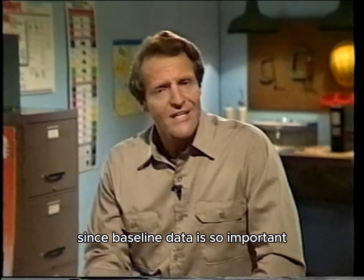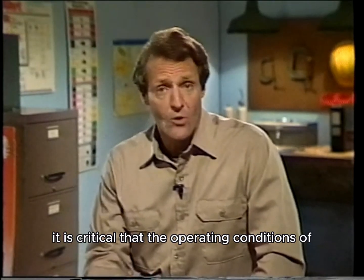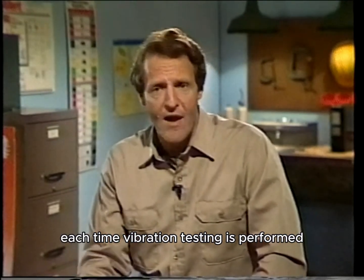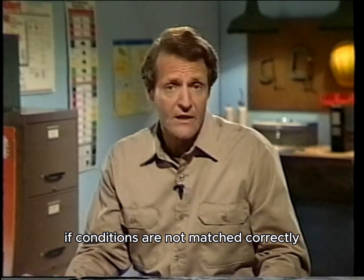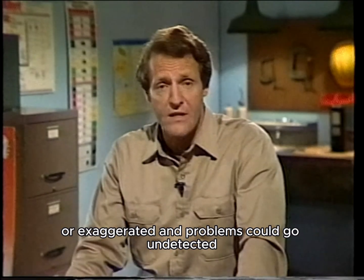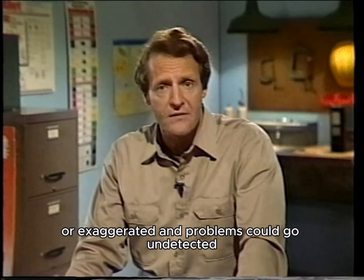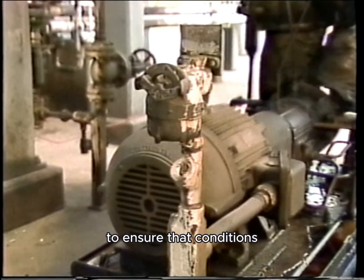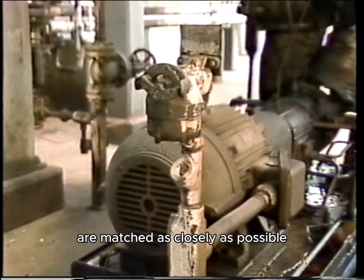Since baseline data is so important, it is critical that the operating conditions of the machinery are the same each time vibration testing is performed. If conditions are not matched correctly, the actual vibration of the machine could be masked or exaggerated, and problems could go undetected. There are many parameters that should be checked to ensure that conditions are matched as closely as possible.